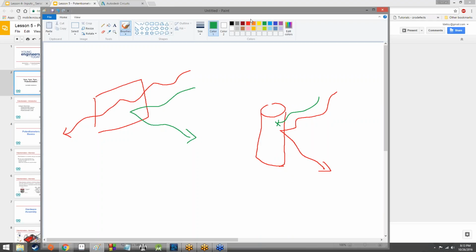So you put an LDR here behind this red cellophane, and then you have a flashlight that shines. Well, it shines through the red cellophane, only red light comes out. It bounces off the red object and goes back into the LDR. If this were a green object, the red light would simply be absorbed by the object.